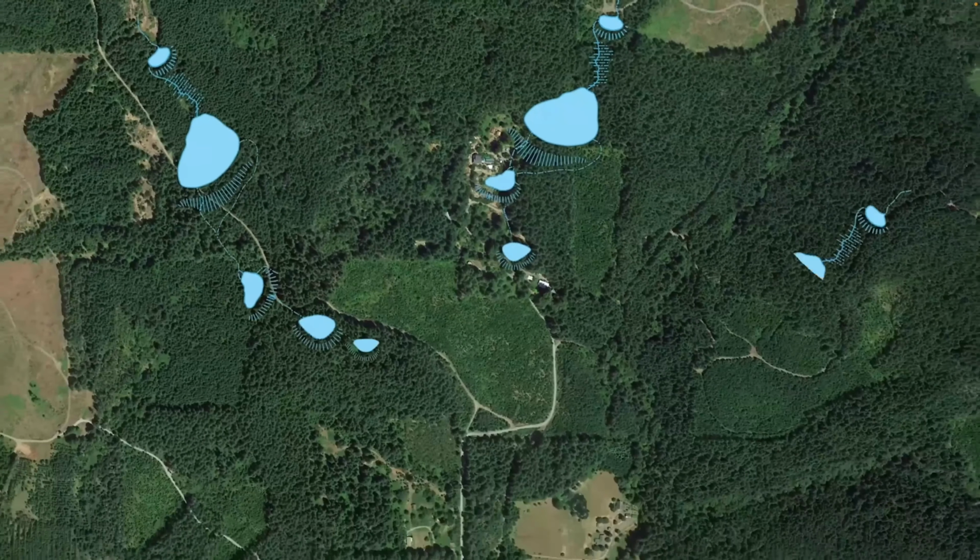It's possible that a really good layer of clay could give way to fractured bedrock or cobbles from a creek bed at a deeper horizon. And so you really want to know the entire depth of your pond. Another possibility is that you find that you have soil that doesn't really suit a condition that leads to a natural seal. So you might have just a very sandy and porous soil all the way down. At this point, you'll need to evaluate whether or not you want to bring in material to seal the pond, or if there's another better, more effective approach to your project.